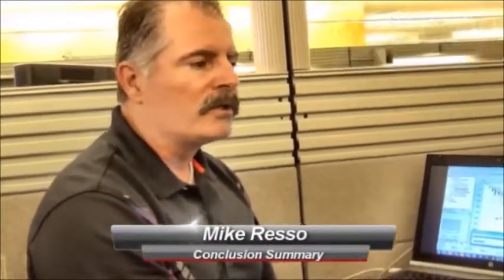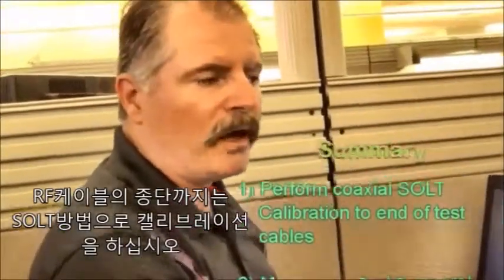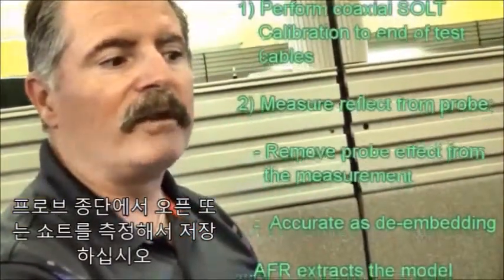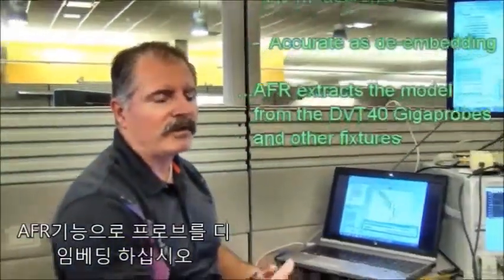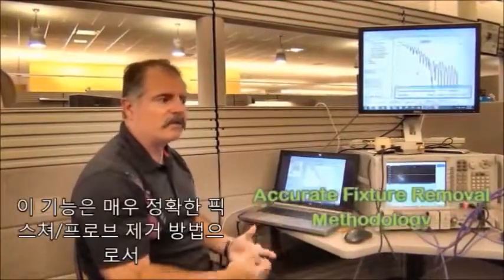And so, in conclusion, what we've shown is probing with a VNA and driving the automatic fixture removal technique with physical layer test system software, we're able to first do a coaxial calibration to the end of the test cables, and then by just simply looking at a reflect of the probe, we're able to remove all of the probe effect, which is just as accurate as a de-embedding, because AFR allows us to extract the S4P information of the probe, which is the model. And so this is a very accurate methodology.